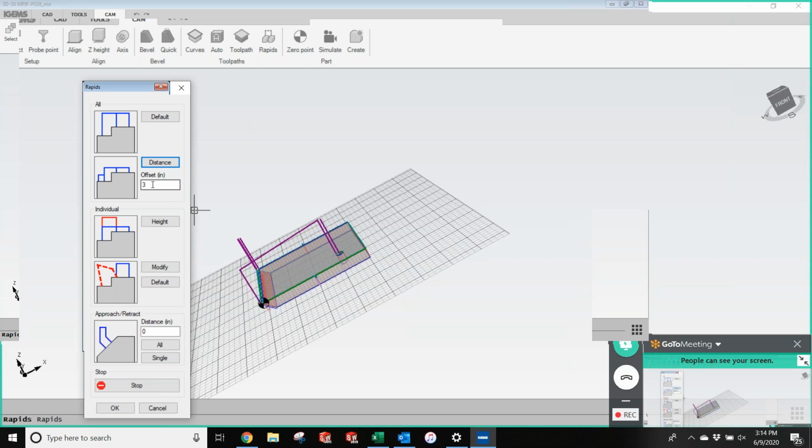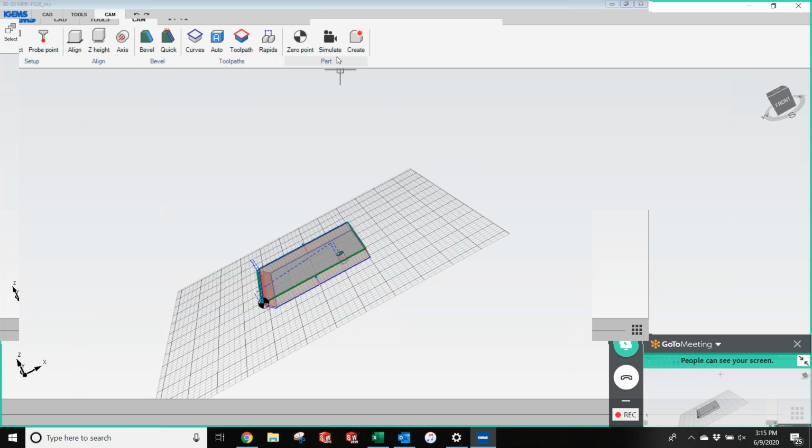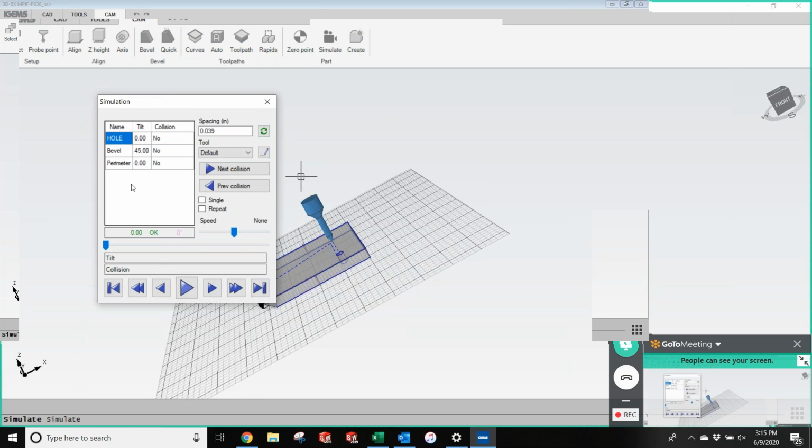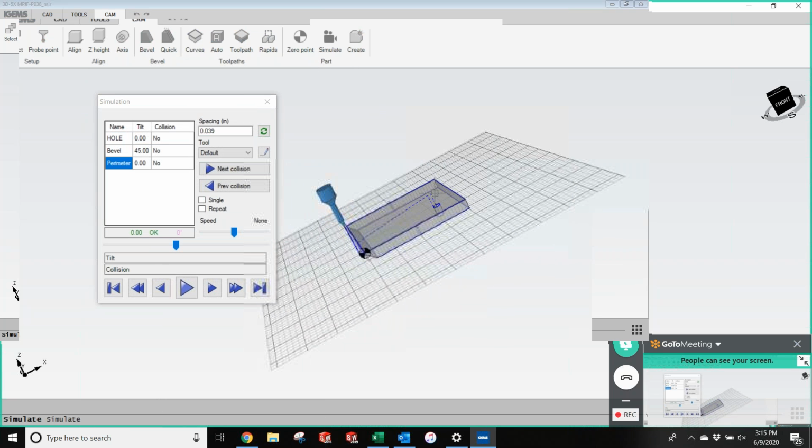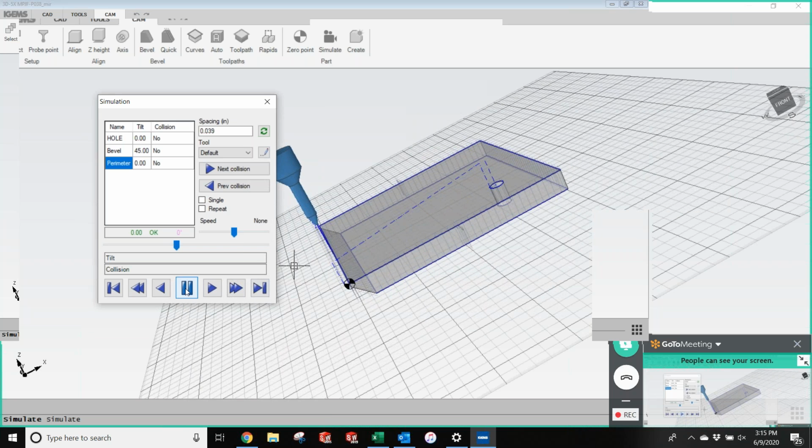Right. So what they did is they programmed it to where it would go up in Z before it started to do the rotation, come back down, go back up, rotate back, and then come back down to make sure that the system cleared any clamping or any other obstacles. Okay. So then we should be okay with the 1-inch lift, sounds like. Yes, sir.